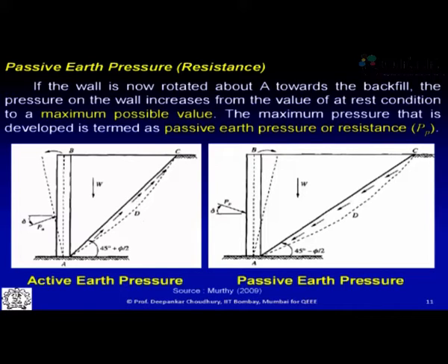process through the mechanics. That is, if I take a soil element at any depth, you can now see in this document camera. Yes, so if you see here, this soil element is subjected to a vertical stress sigma V and a lateral stress sigma H, assuming these are principal planes. Now if I want to draw this state of stress in the soil through Mohr circle, what I can do here, let us look.